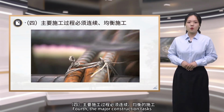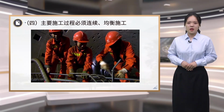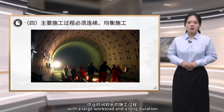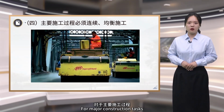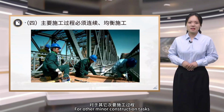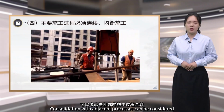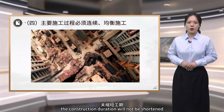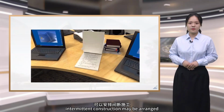Fourth, the major construction tasks must be constructed continuously and evenly. The major construction tasks refer to tasks with a large workload and a long duration. For major construction tasks, continuity and balance are essential. For other minor construction tasks, consolidation with adjacent processes can be considered. If the tasks cannot be consolidated, the construction duration will not be shortened. Intermittent construction may be arranged.